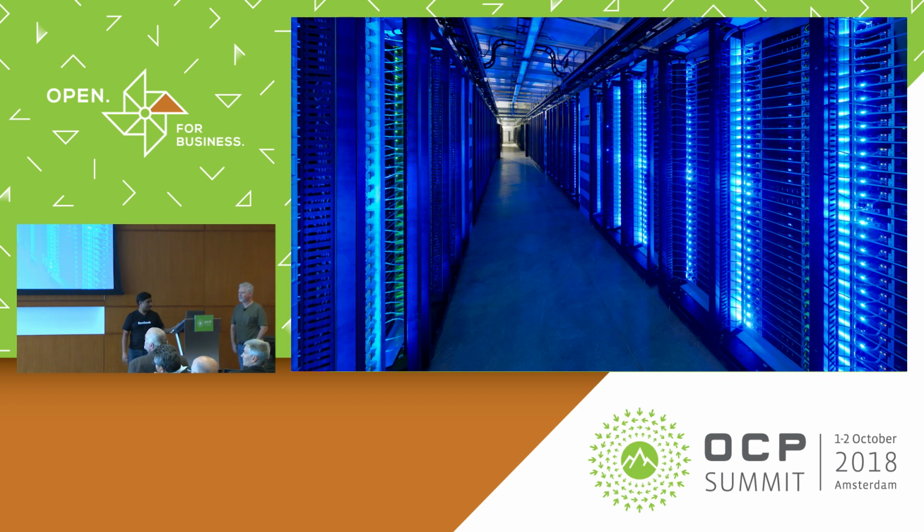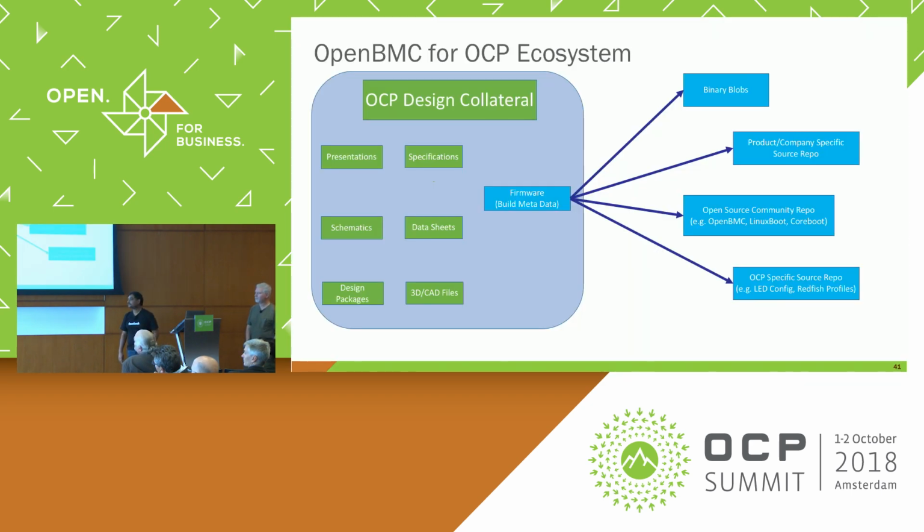Earlier, you have shown two examples of the BMC SoC. Right. We have to use it in order to support BMC. Good question. Today the primary supported one is ASPEED, and Nuvoton is pretty actively working on it. So they are part of the ecosystem. They contribute all the kernel patches, and they're very actively contributing to that. So the idea is today we have one or two SoCs, but as more SoCs come into play, they should be able to contribute their code and make sure the BMC is agnostic to the hardware.